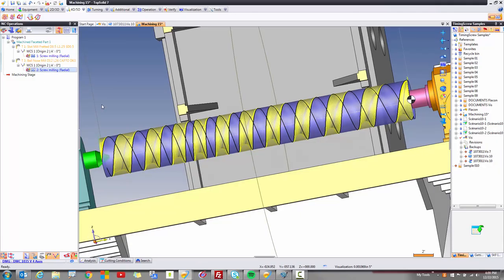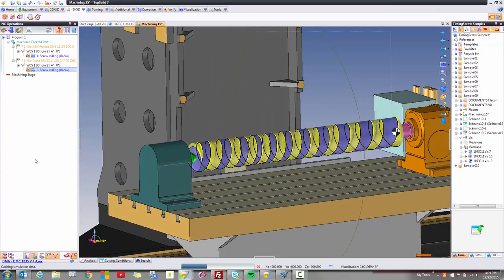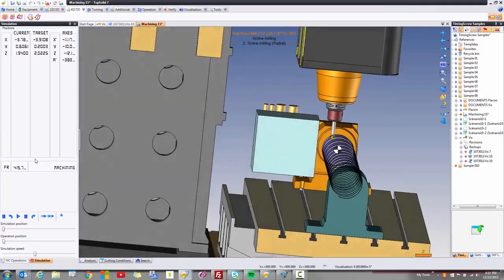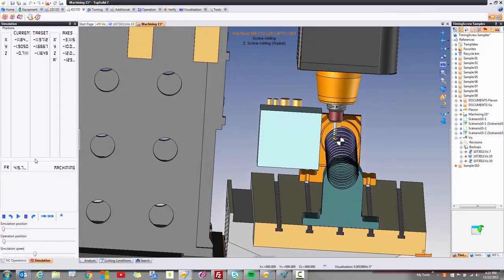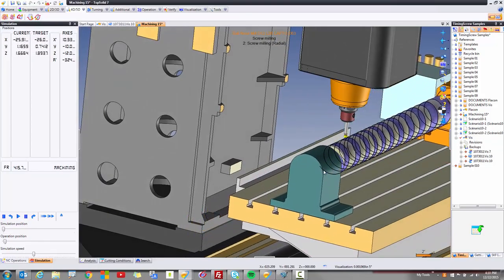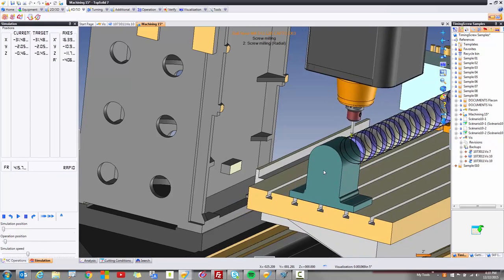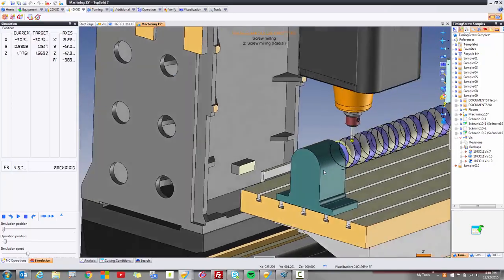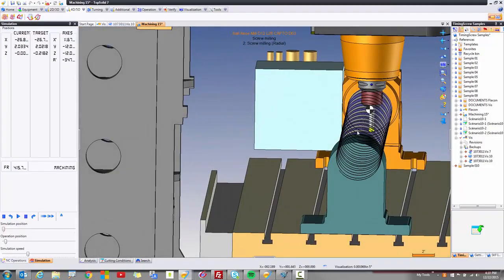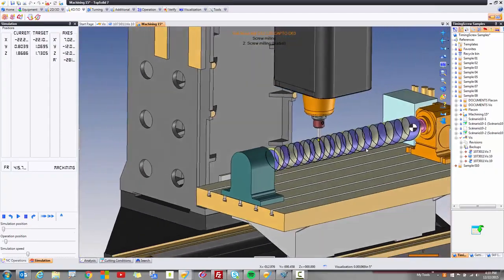And we're done. And now you can see the finishing toolpath. Looks pretty nice. Let's watch the simulation, see what it does. So here I'm going to watch the simulation. You're going to see that we come down on one side, and you see how the tool is off to the side there? Perfect. Now watch what happens when we come back on this side. Once we get down there, I'm going to slow down a little bit so you see it. Now what will happen is we're going to offset back to the other side, and notice we're cutting back on the other tooth, or the other side of the tooth, with the tool now on the front side of the part. So not wasting any motion going back or forth.